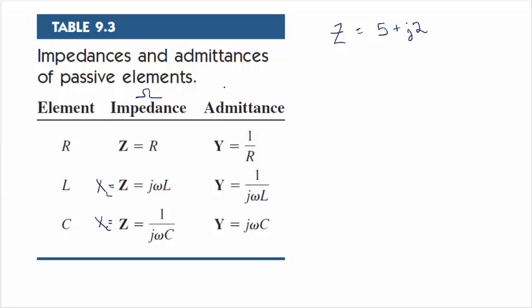or admittance is in units of 1 over ohms, which some people call mhos. Yes, I'm not kidding, it's ohms spelled backwards. Sometimes the more official unit is the Siemens, but you will hear it also called mhos.